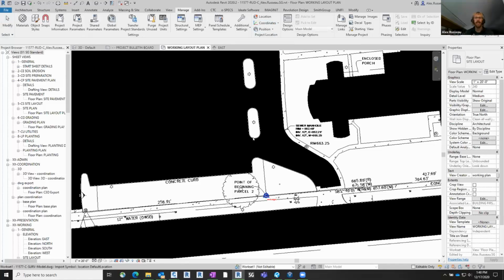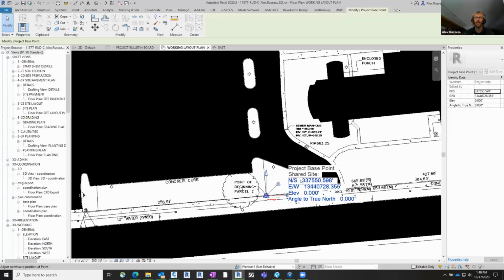All I'm doing is, sorry, I went a little quick, but it asked to select a link. I click the CAD file and it happens automatically. If I click this point now, there we go. We have a northing and an easting that are set up to match our real world coordinates. You'll note now though that the elevation is at 0. So this is that one thing that Nick had talked about earlier, to make sure you're coordinating with the civil engineer to set up that Z.